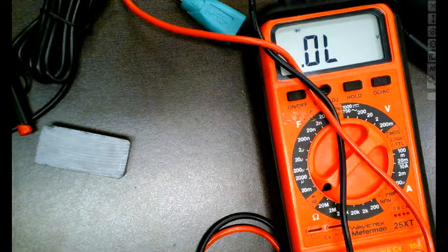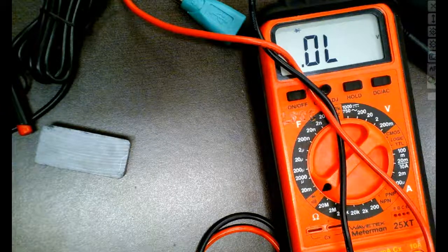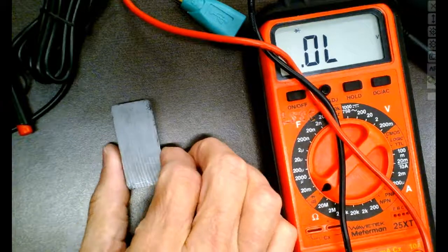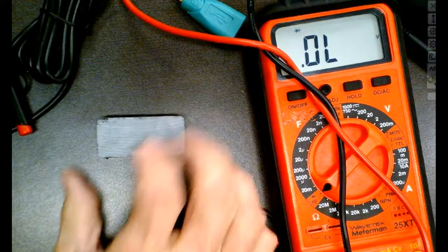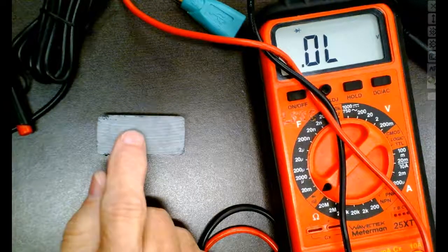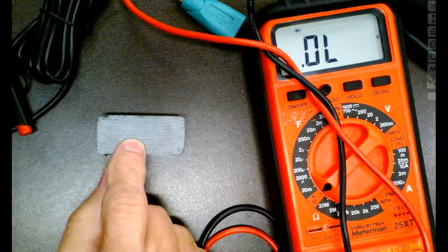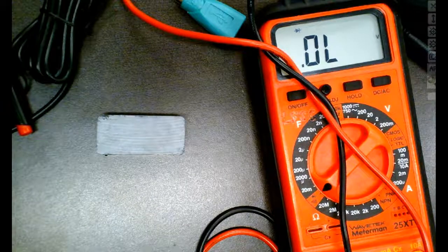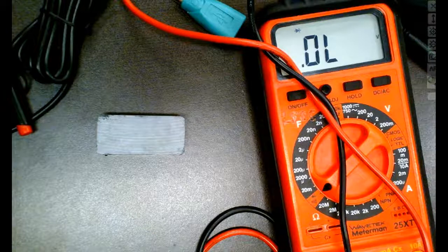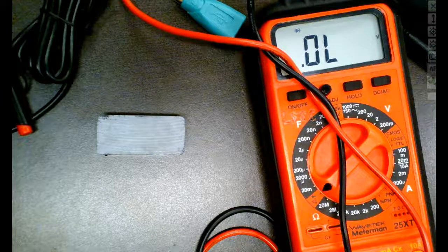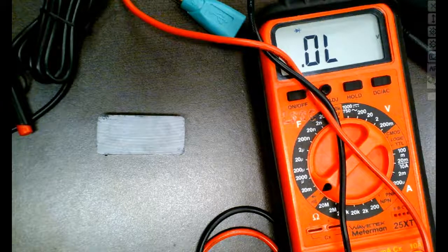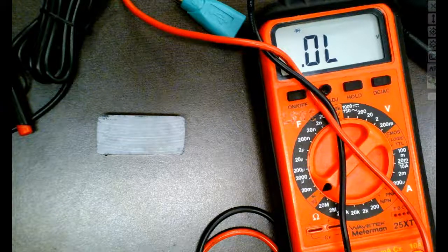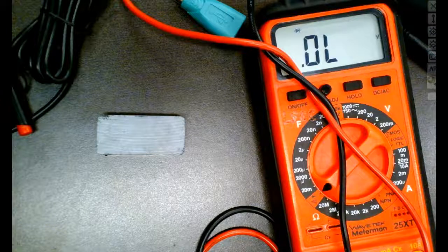The biggest advantage of magnetic reed switches is that they're very cheap, real cheap. So what we would do, what's in motion, we would mount the magnet on that, and then stationary, where we're trying to sense the proximity, that's where we would actually press the reed switch. That way we can make electrical connections to the reed switch because it's not in motion, right?